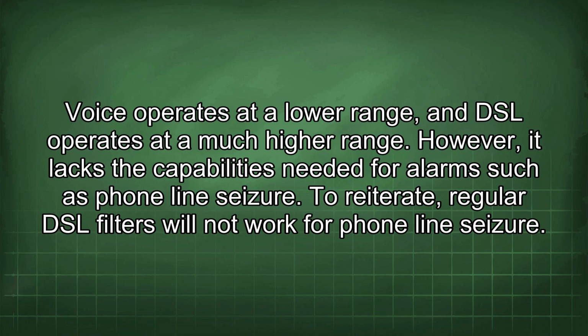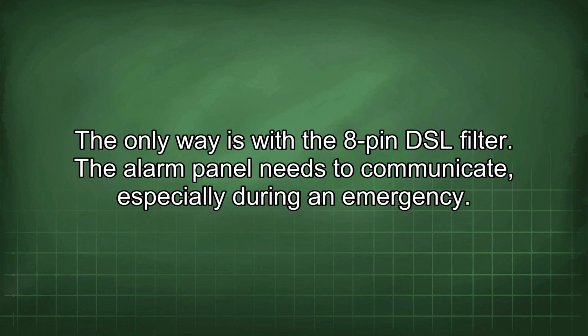To reiterate, regular DSL filters will not work for phone line seizure. The only way is with the 8-pin DSL filter. The alarm panel needs to communicate, especially during an emergency.